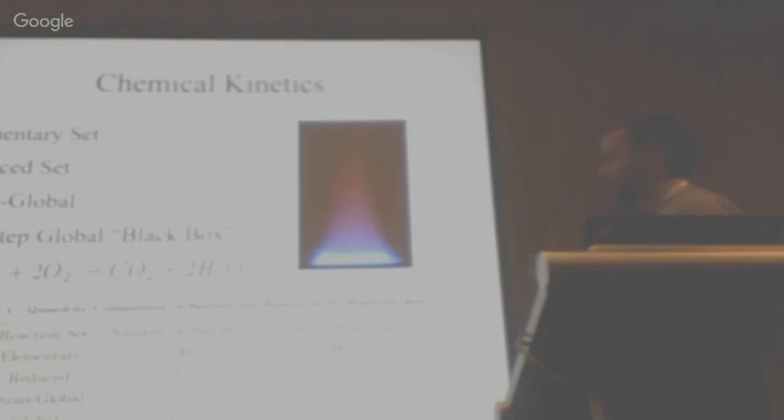This kind of is something that your high school, balancing equation, old stuff can kind of wrap its head around. Basically, the left side of the relation goes into a black box and out pops the other side. All humor aside, this is still valuable. When the proper Arrhenius rates are used, you can get good fits to experimental data for flame speeds, which are basically the rate at which a chemical will burn. So for certain CFD applications, this is still really valuable and still keeps you within reasonable computational expenses.